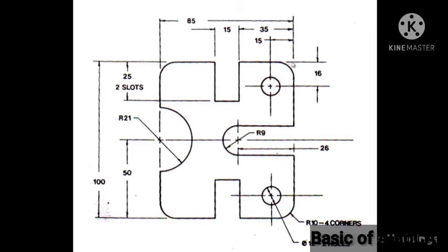And how will you define the upper right corner? For that, you have to go through the figure and locate the maximum dimension. The maximum dimension is 100 units in this. So you have to define the upper right corner in such a way that its value is above the maximum dimension to be plotted. Since the maximum dimension is 100, you can give a value something like 125 or 150.